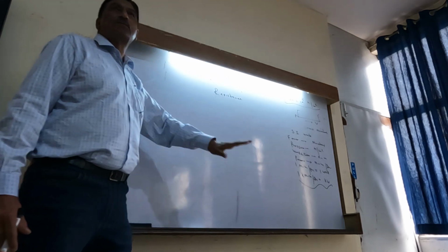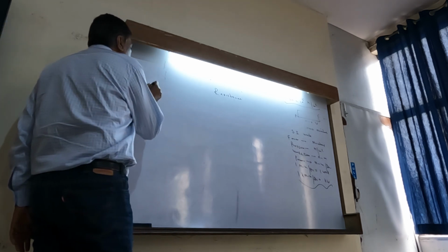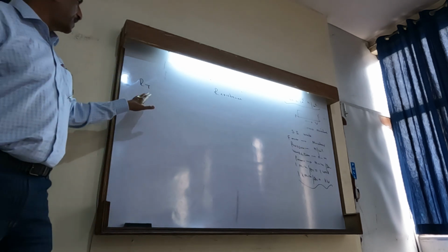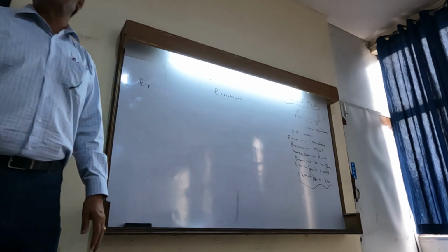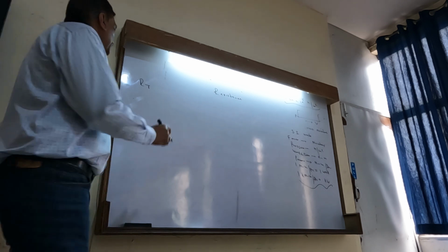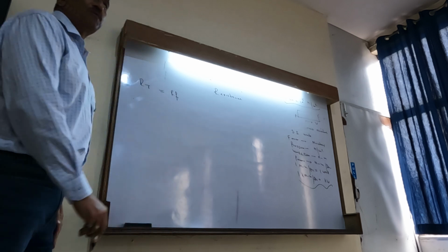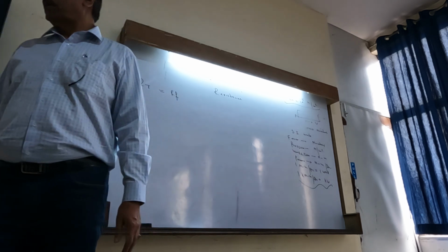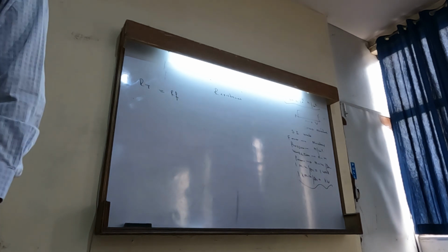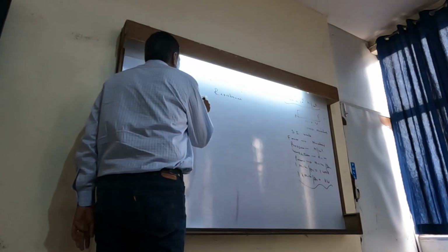This resistance has got two components, and that is why we say RT is the letter we use for the resistance, where R is the resistance and T represents the total resistance, because resistance has got two components. One is called frictional resistance, RF, which is because of the friction between the water molecule and the steel, and we are assuming the ship is made of steel. Plus, the second type of resistance is called RR.